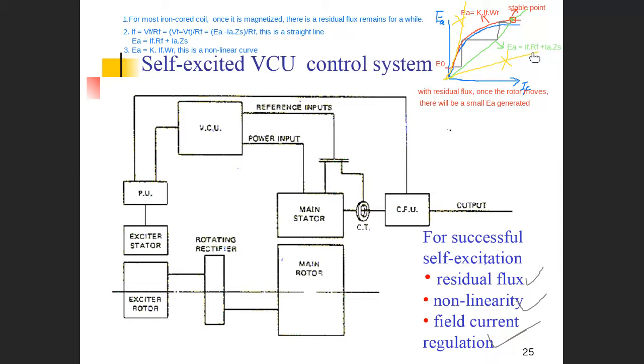Because you can determine the RF with different values, the relationship we show here, the second point we show here, has different slopes. With some slopes, the generator cannot start properly. With some slopes, the generator can start, but cannot stabilize at all. They wait a very, very long time to stabilize.